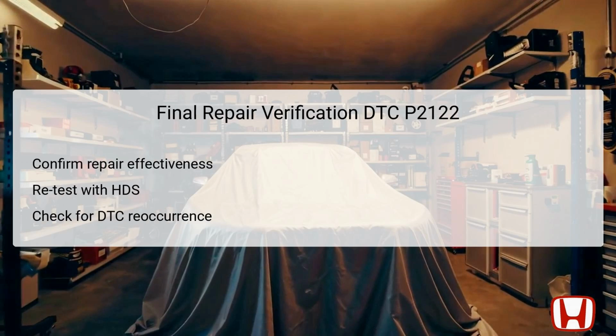After completing all necessary repairs and component replacements, it's vital to conduct final verification of the repair process concerning DTC P2122. This begins with a thorough retest using the Honda Diagnostic System HDS to assess whether the repairs have resolved the issue. The technician should closely monitor voltage outputs from the APP sensor, ensuring that they now meet the specified operational parameters. Additionally, it is crucial to clear any previously logged DTCs and recheck the vehicle under various driving conditions, ensuring that the DTC P2122 does not reappear.